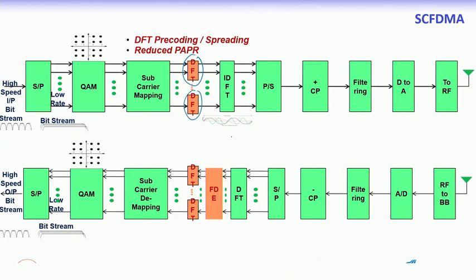If you have, let us say, 1024 carriers in the IDFT operation, then one would like to add DFTs of various sizes to get various benefits. One could think of a 128 size DFT. If one does a 128 size DFT, one would have m number of such 128 point DFTs that would result in a 1024 point IFFT mapping.